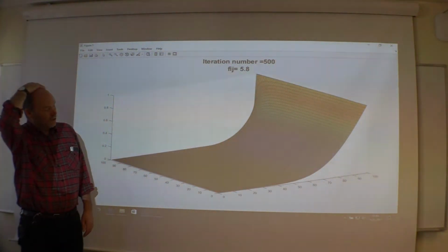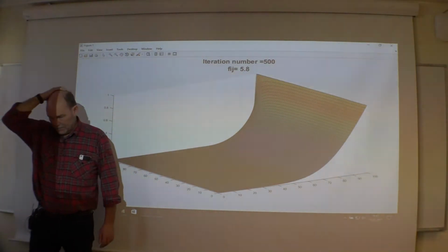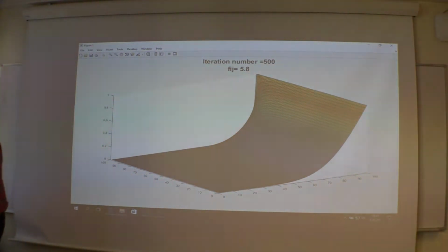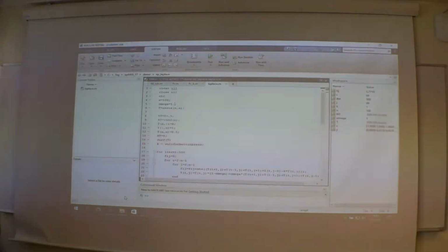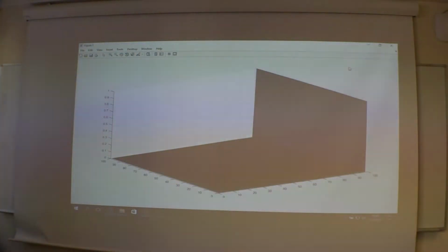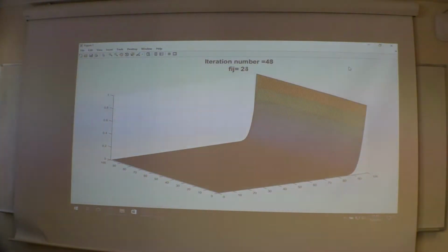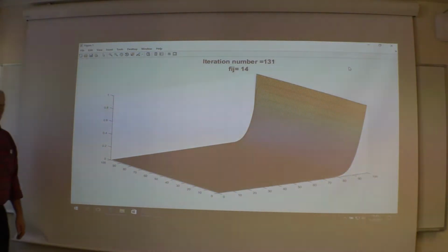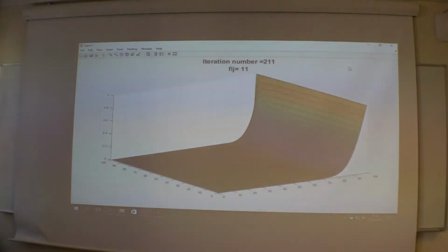And it's way off in the end after 500 iterations. And of course, using omega smaller than 1, say 0.6, as an under-relaxation, yes, you can do that, but why should you? Now it's even slower, so this is going to take forever. So it's a very, very bad idea.